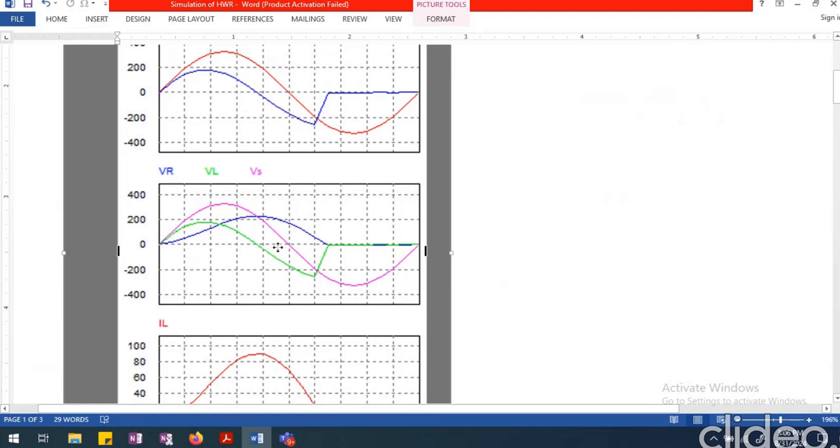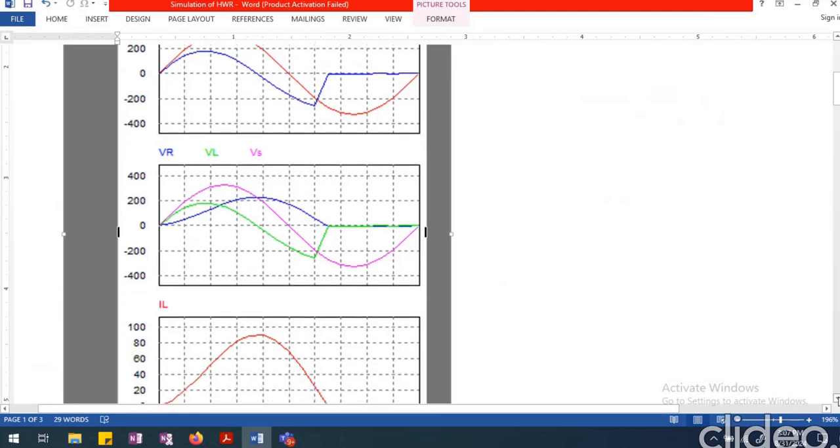This volt second area seen here is actually the energy given back by the inductance, and this is the energy taken in by the inductance. So the energy stored by the inductance will be equal to the energy given back by the inductance in an RL circuit. And you can see the current is even continuing beyond the positive half cycle.